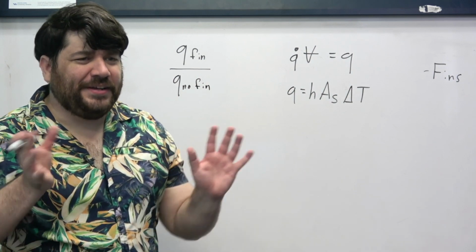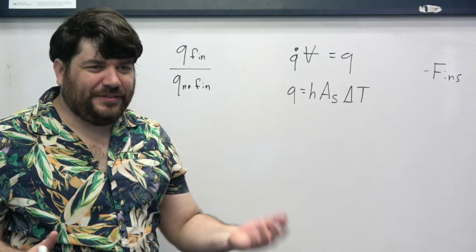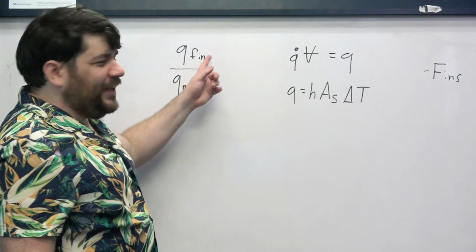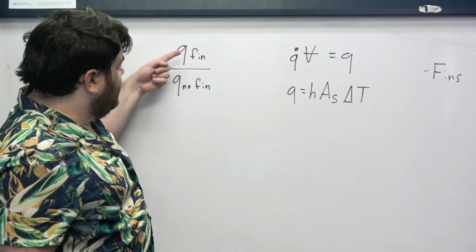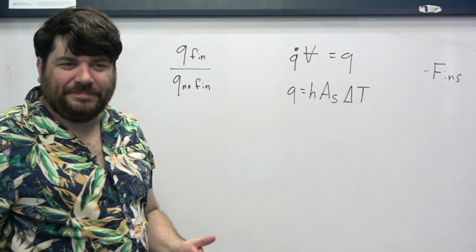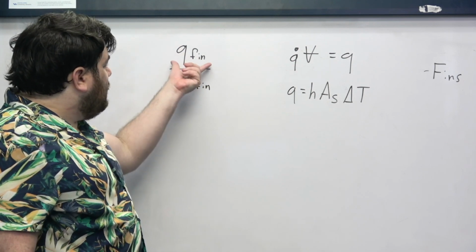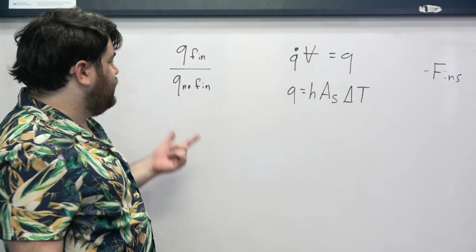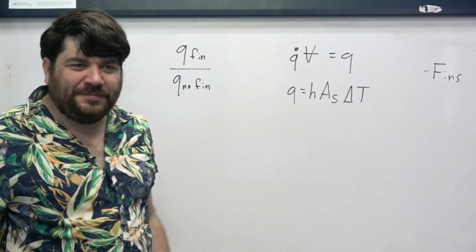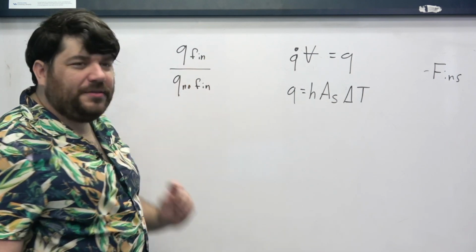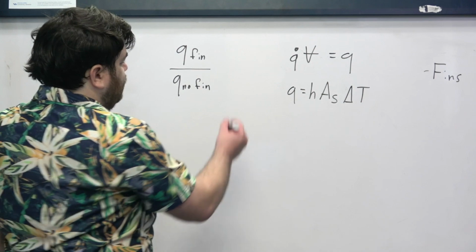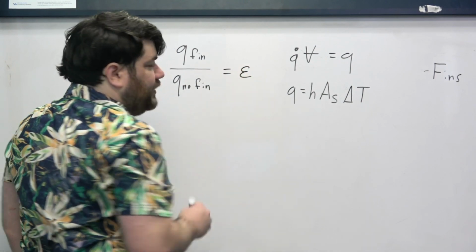This is a very pure and obvious way of knowing whether or not the fin is good, because we are just relating how much the heat transfer rate goes up. Like how big is the improvement of the heat transfer relative to the base rate with and without the fin. And we usually call this the effectiveness, right?